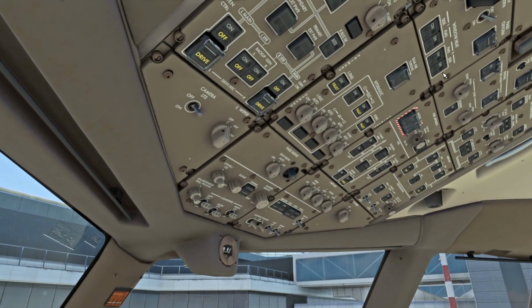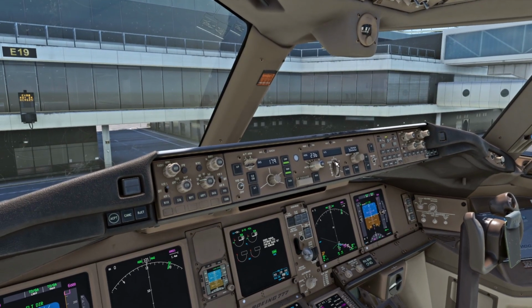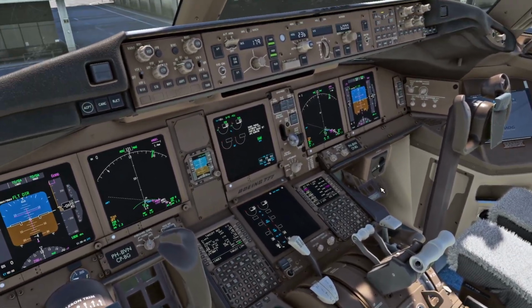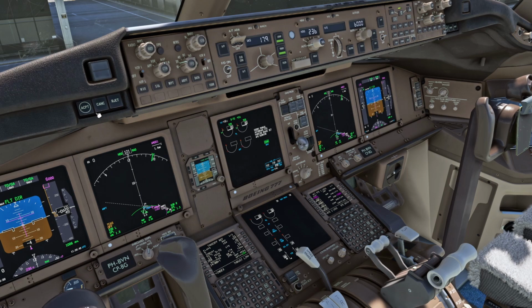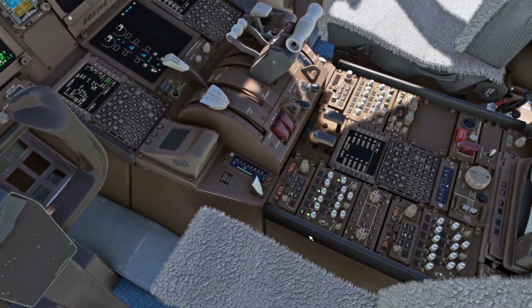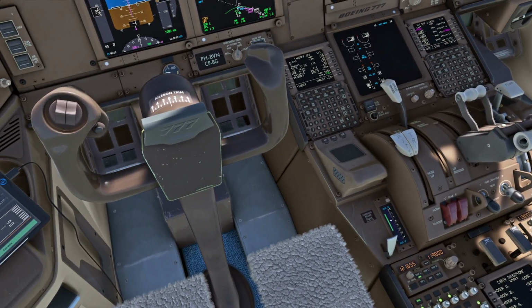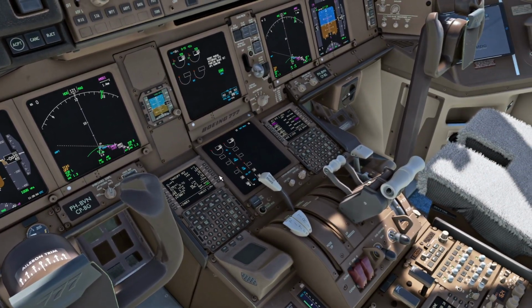Turn on the hydraulics, seat belts, fuel pumps, beacon lights, give a little recall check, and then the TCAS. And then do the captain flow by setting the MCP after confirming the load sheet and setting the trim, and also the trims here as well, the rudder and the aileron trim. Make sure you include them in your scan flow.